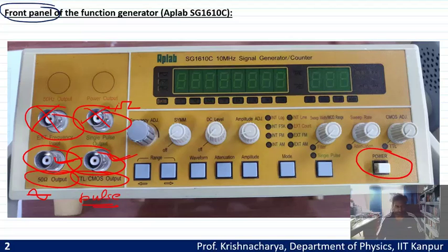Now you connect your BNC cable to your actual output, either this one or this one, and then take the output to the right position. For example, if you want to give this signal as an input to an op-amp or any other device, transistors for amplification or whatsoever, you will be taking the signal from here. Now the signal should be of which form?